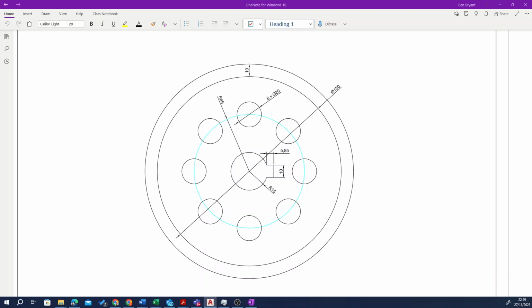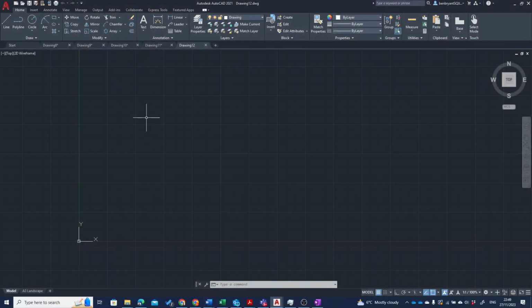So running from the center, 0, 0, you've got a couple of features that you might want to consider. There's the diameter of 150, and then you have your radius of 45, which will give you that working blue line. Those are the two areas where you have to start to get your crucial dimensions from. So from your drawing, quite simple, straight into the circle tool. CI for circle, 0, 0, because we're working at the 0 point.